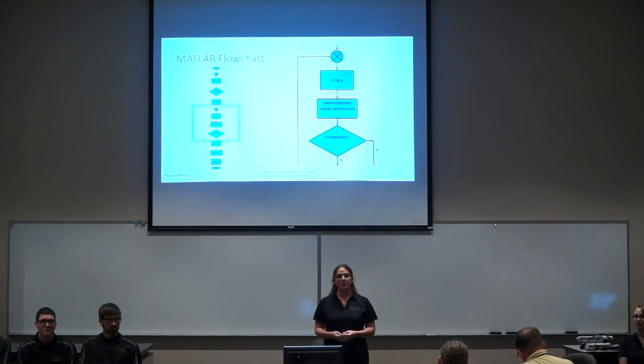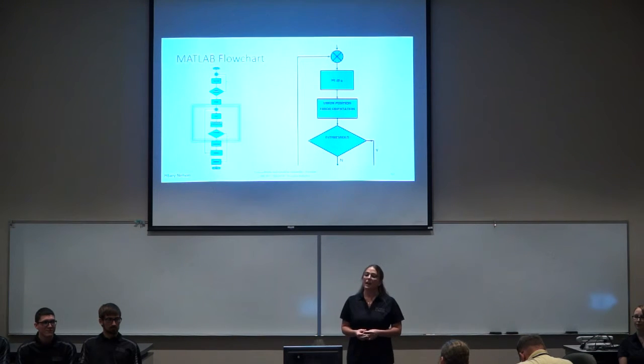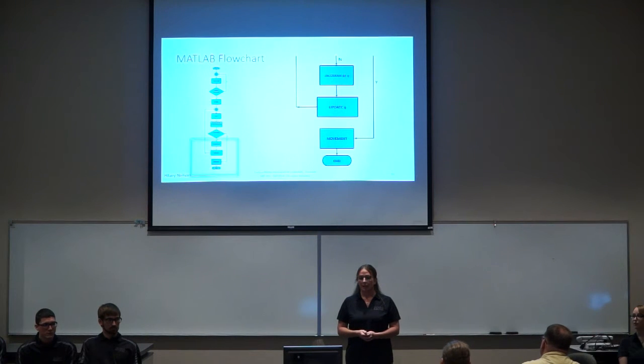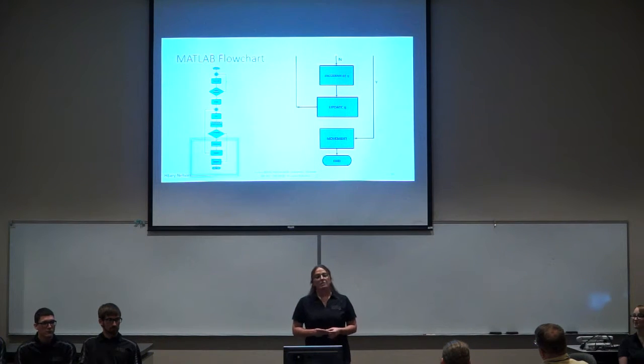Next, we calculate the forward kinematics, which enables us to find the joint velocities. After that, we check whether our error in position and error in orientation has reached its end point. What the error means is whether the robot is within a certain threshold of finishing its task at hand. If it's not there yet, we continue on, and we calculate, using the damped Jacobian pseudo-inverse algorithm, the joint velocities that are needed.